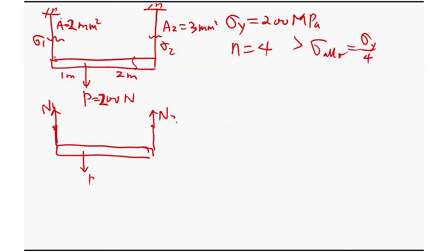and then this is the force we don't know, we just call it N2. I use N, I don't use P. You notice that? The reason is I want you to distinguish the internal force versus the load. I want to emphasize, make sure your mind is on looking for the internal force. This tension, I don't know. I assume it's tension, right? I'll find out if it's negative, then it's not tension. But based on my intuition, it should be tension. You find something there, it's never compression, right?